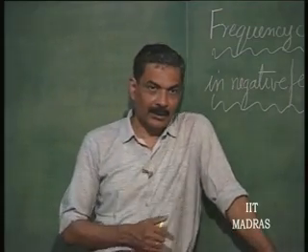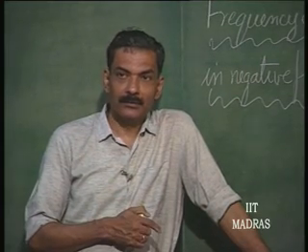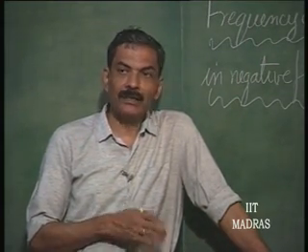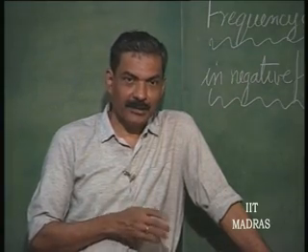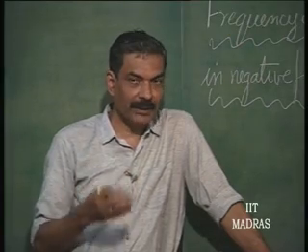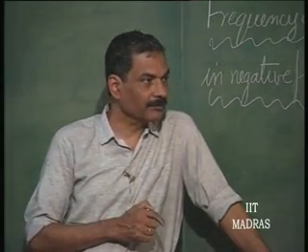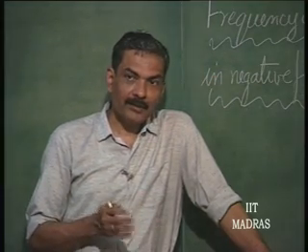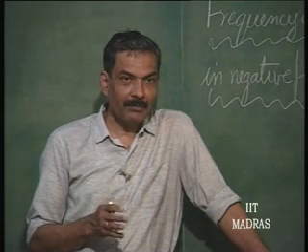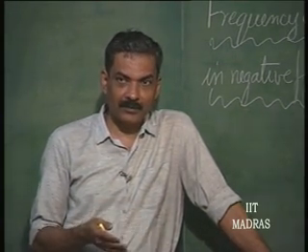Let us understand. We can give negative feedback in order to make the amplifier go towards its ideality. Depending upon the type of control source, it can become a better control source with negative feedback. This is the purpose of negative feedback. Positive feedback should not be attempted, primarily because it will make the gain or transfer parameter more sensitive to active parameter.